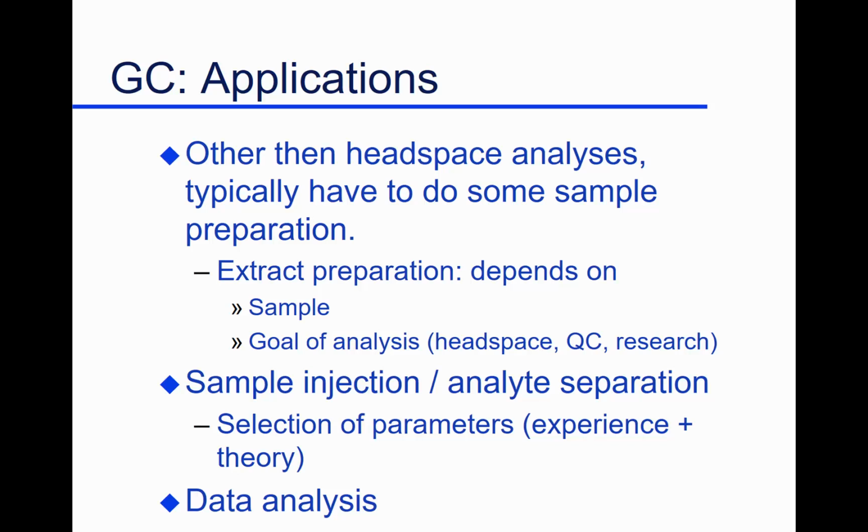I can put that milk into a bottle, seal it up, and allow it to come to equilibrium. All the aromas come into the headspace in the bottle. I can just take a syringe, go through the rubber septum on top, draw some of the air, and put it into my gas chromatograph. That's how you look for off flavors, or do quality assurance of foods. But that's the only technique where you don't have to do any sample preparation.